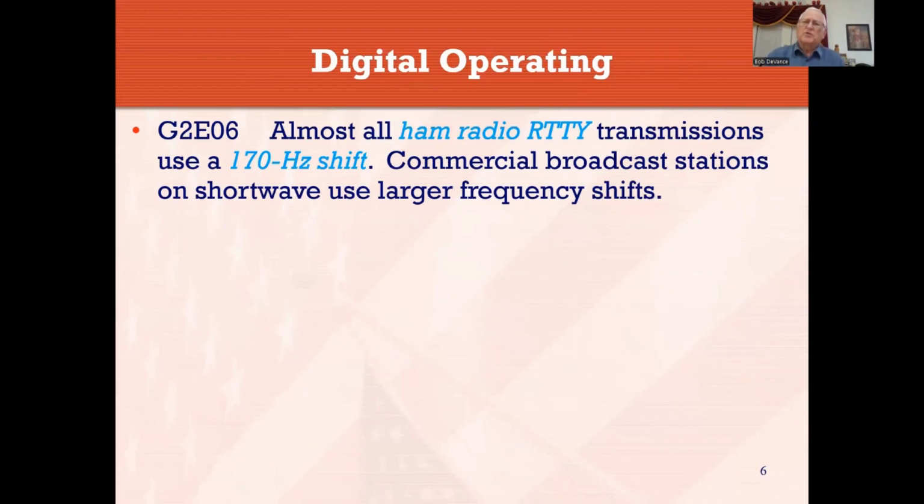You know, we talked about frequency shift earlier when we were actually shifting the carrier frequency. And on this, we're not shifting the carrier frequency, we're shifting the audio frequencies that ride on top of the sideband carrier. So when we say we're doing frequency shifts, that's what we're talking about, just shifting the audio tones. And we're using the two tones for RTTY radio teletype. 170 hertz will stick out like a sore thumb when you see the question.